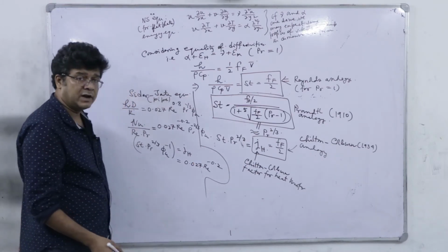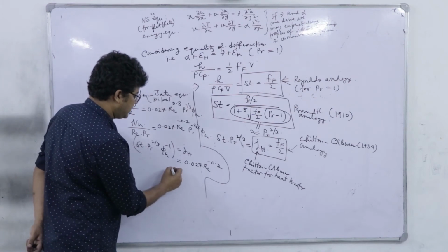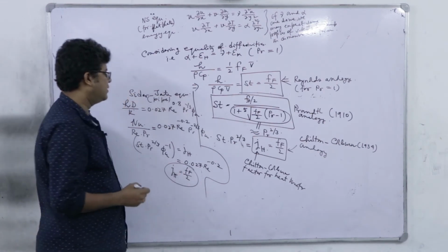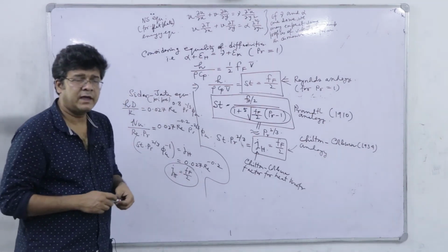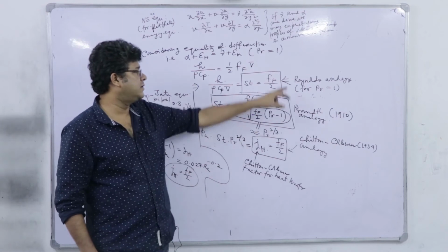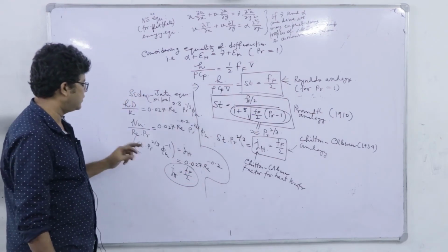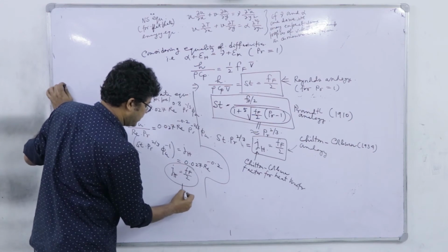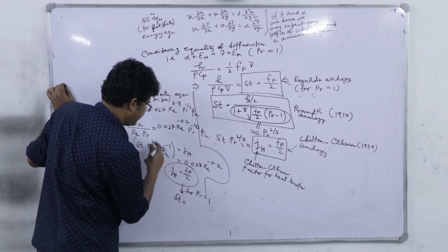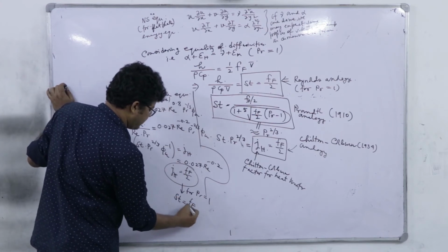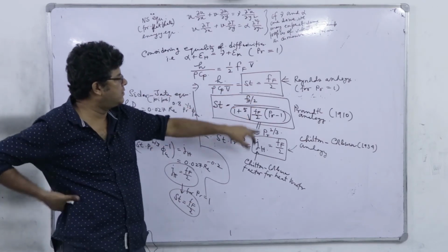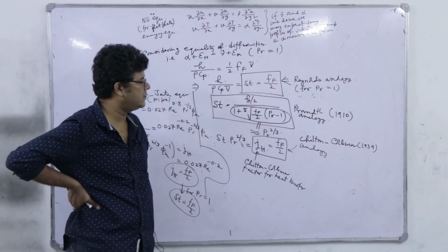And from Blasius correlation of Fanning's friction factor, that can be established to be equal to f by 2. So, this is typically the formal way of getting the Chilton-Colburn analogy in an easy manner, right. All this analogy, the Chilton-Colburn analogy also reduces to the Prandtl analogy, this Reynolds analogy, for Prandtl number equal to 1. It gives you Stanton number, phi u is neglected, simply equal to Ff by 2, right. So, you see that we have just jotted down the three analogies, Reynolds analogy and Prandtl analogy, or this Chilton-Colburn